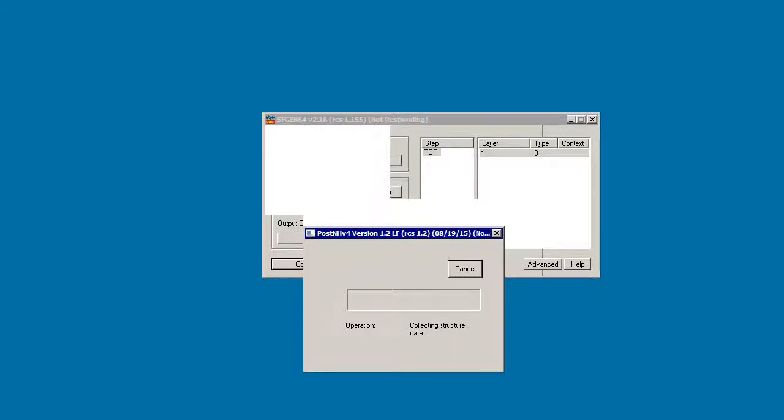Now it's actually looking at the individual structures and processing the structures and their children. This program takes advantage of repeating data. Most of your large panels consist of a small circuit that's been repeated hundreds or even thousands of times. If you know that, you can avoid doing a lot of things by brute force. The data that's not repeating we call the frame. We have to process that brute force, which is what's going on right now. Once the frame is done, we'll be able to merge the results of both the step data and the frame data. Then we'll have our final output.